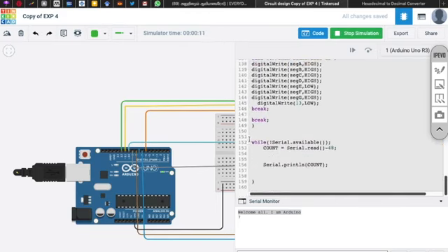is wait for the serial data to be received. Until I type 5, it waits at this line number 152. When I type 5 and send, the data is transmitted from the PC to the Arduino. Once it is transmitted, the Arduino receives the data, converts it to the decimal value, and prints it, or echoes it back to the desktop or laptop. That's why I have received 5 over here. Whatever data I transmitted, I received back over here.